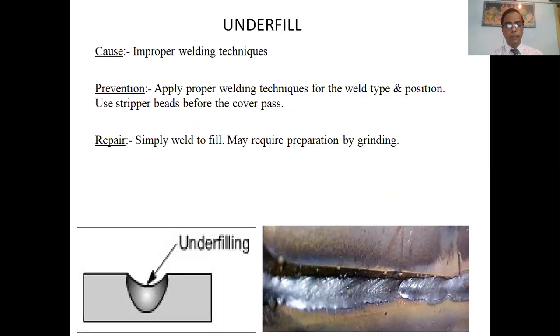Underfill. This is underfill. It is not filled up properly. Cause: improper welding technique. Apply proper welding technique for the weld type and position. Use a deeper bead before the cover pass. Repair: simply weld to fill. May require preparation by grinding.